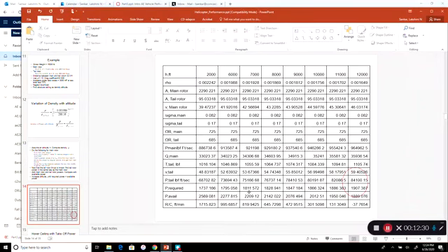So if you do that, here are some details of the calculations. Pick several altitudes, several densities; that area does not change. Induced velocity increases as the density decreases because it's inside the square root. Solidity does not change, omegas, these don't change. Then the main rotor power, profile power plus induced power, is this. Torque is profile power divided by omega in radians.